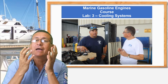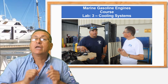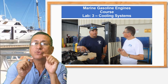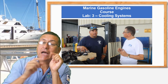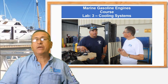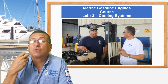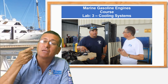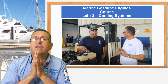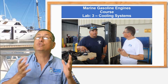Okay? I need you to analyze both types of inboard engines and both types of refrigeration. Especially, I need you to focus on the path of the coolant and the path of the raw water. This is important, my friends, because in the future, you will receive a lot of calls related to temperature problems in engines, and you need to identify immediately if the engine is a raw water system or a closed system with heat exchanger,